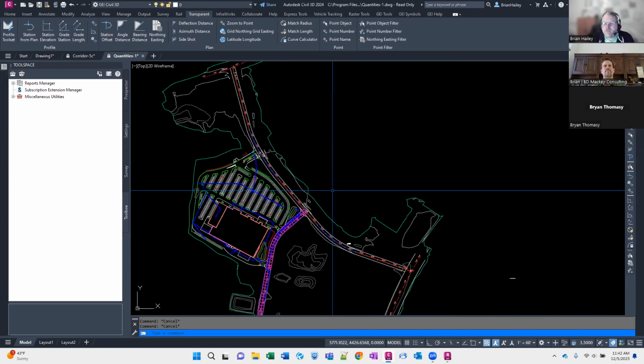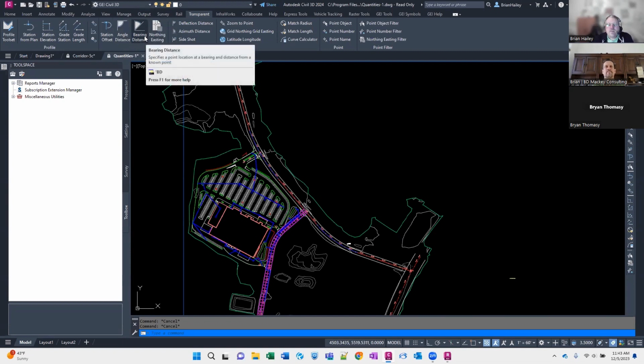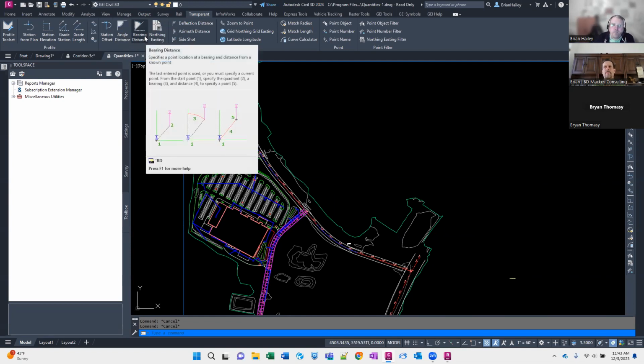Another example, as I was going to show before, is if I have to recreate a boundary based off of a plat where you've got all of the thences. Thence north 45 degrees, 12 minutes, 13 seconds west at 437.21 feet. Thence, right? So we have, let's see, there it is, bearing and distance. So again, this is asking you to calculate a pick point based off of data that's in the drawing.